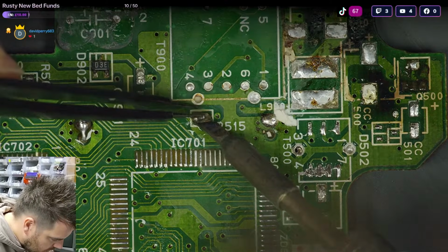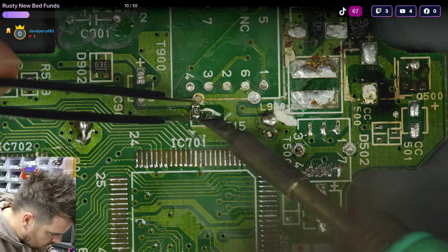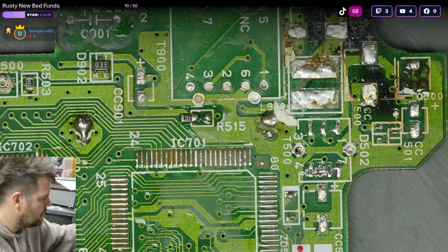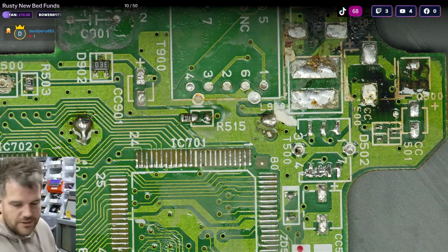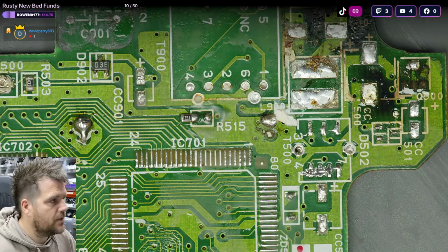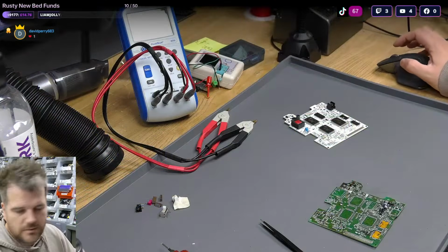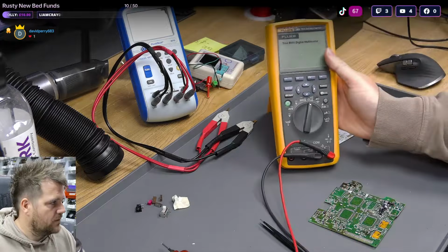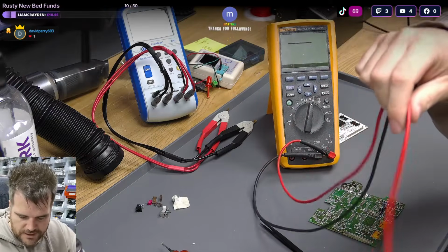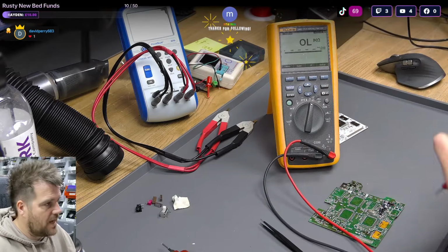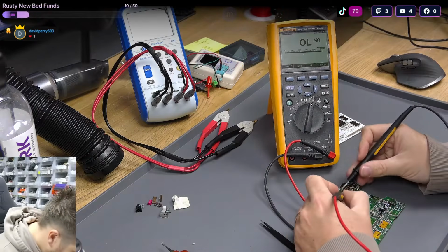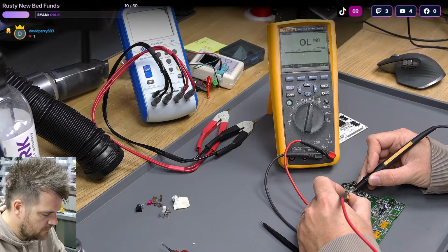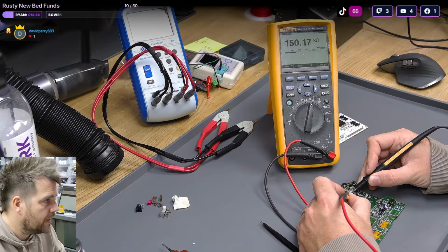So to test this off circuit, I'm just going to move this off. To be honest, I originally said I wouldn't use these components. We'll swap them for new on this board, but we're literally testing them, so that's kind of the point, to test they're okay. So for this one, I'll put the components on. It saves me a bit of time hunting for every single resistor of a specific value that I might not even have. So now we can test this equivalently as if it's not on the board, because one pin's floating. And there you go, 150k.